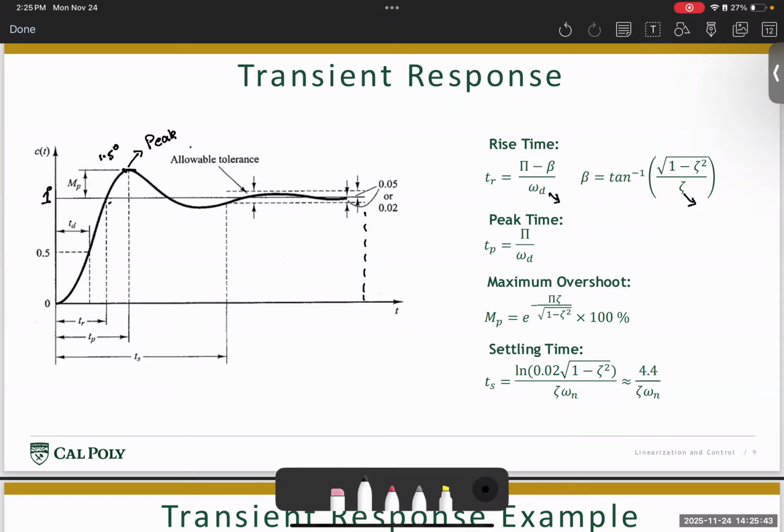And then the last quantity we're going to discuss is called settling time. Settling time is basically the amount of time your system takes to start from the time instant where you provide control, in our case at time t0, until it reaches the desired state of the system, which is the instant where the aircraft's pitch becomes, let's say, 5 degrees or 1 degree based on our reference signal.